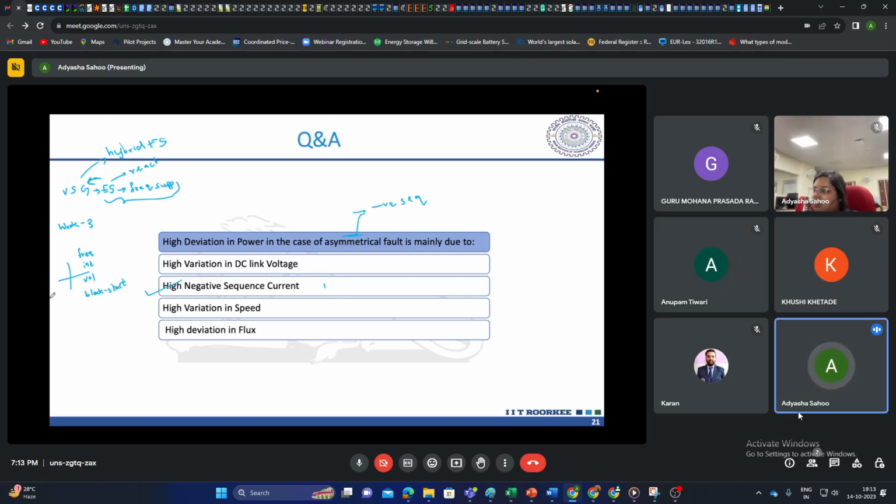Battery energy storage, can you repeat? No, see, it has to be a hybrid storage because if you remember, the energy storage were of high energy and high power type. So if we choose battery, we are basically implying high energy type. So a high energy type of storage will not be able to give all these services.